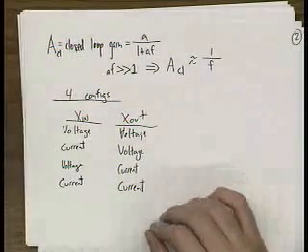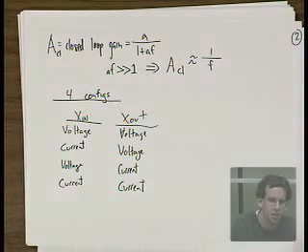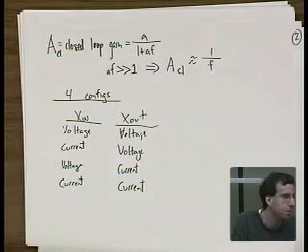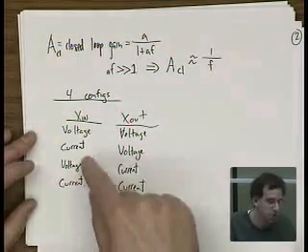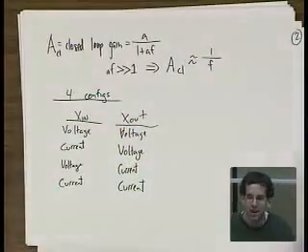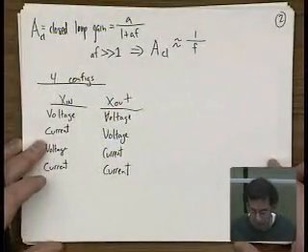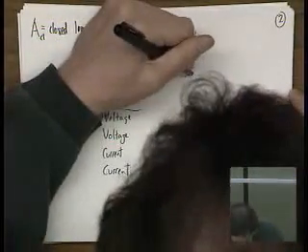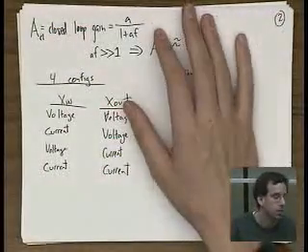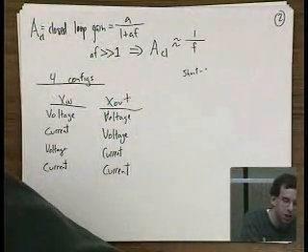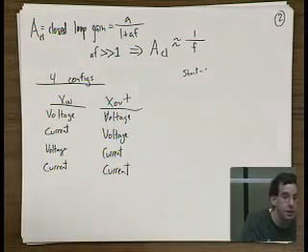So if you've looked at the Gray and Meyer book and the standard terminology, which Professor Brodersen uses in his notes, it talks about feedback networks in terms of shunt and series. There's a direct correlation between whether the inputs are voltages or currents, but it's not necessarily clear why or how, and I wanted to explain how. So when we talk about, for example, a shunt series network, the first term is basically referring to what quantity you feed back.